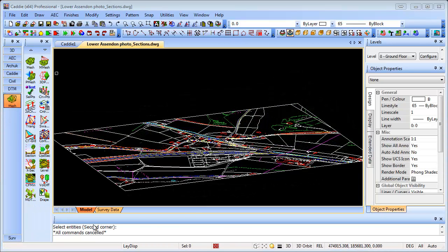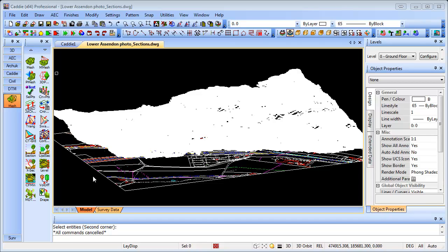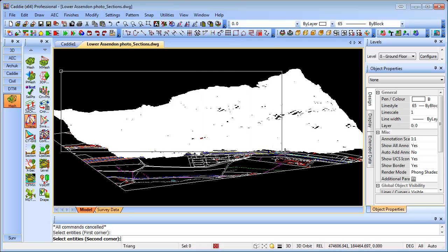Here we've imported the ProMap site mapping data, so our site plan if you like. We can also take on board the height points, here on a regular grid, so we can have either the DSM or DTM, digital surface or digital terrain model. Then using our triangulation tool within the DTM application, we can convert all of those points, or all of the ones that we want to, simply by dragging an enclosing rectangle around them, into a 3D tin.